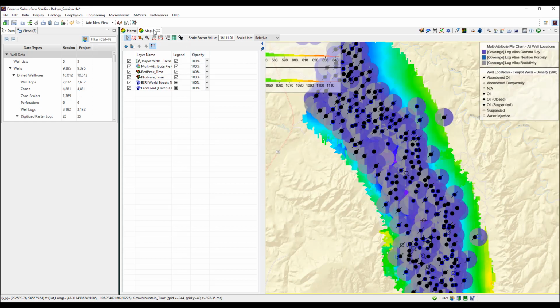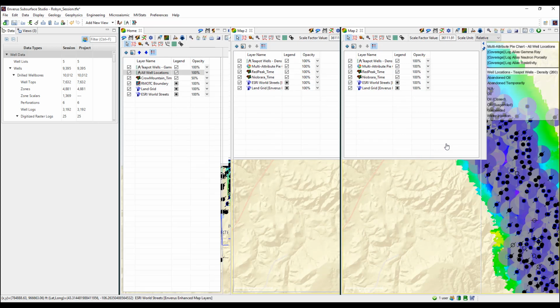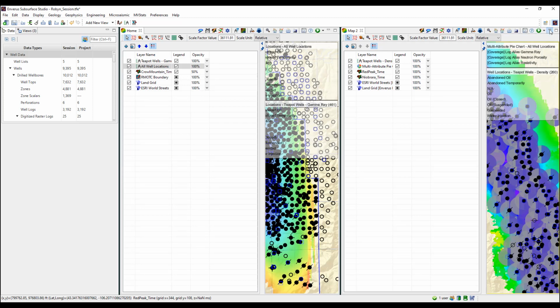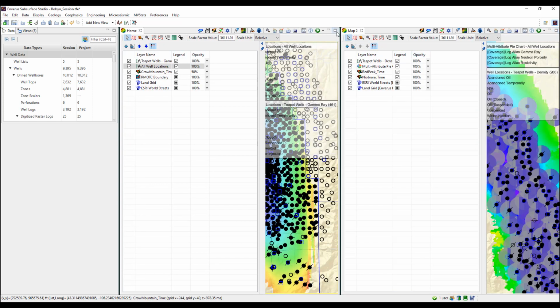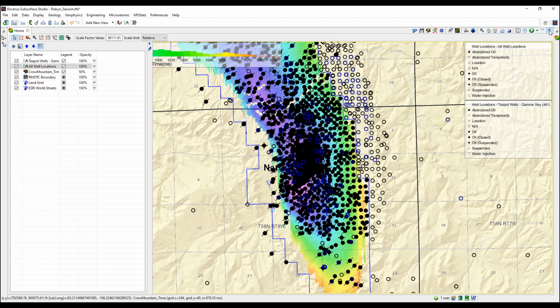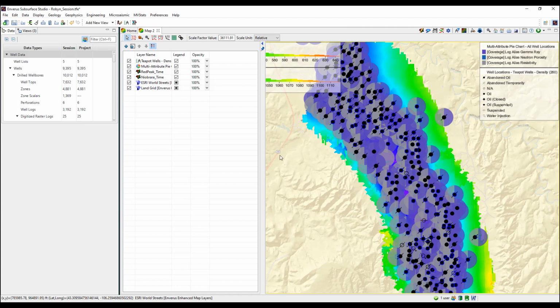Any panel in ESS may be relocated by left-clicking and dragging its title tab. For example, a user may view 2 display panels simultaneously by dragging one of the tabs towards the edge of the main ESS window to split the workspace. Panels may also be maximized and reset by double-clicking their respective tabs. Take care when moving panels to avoid missteps.